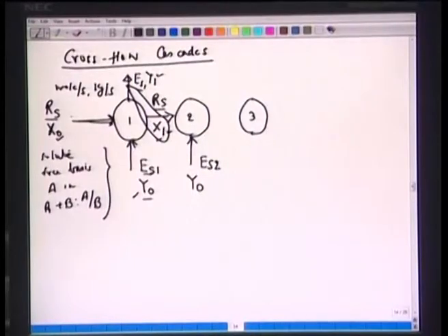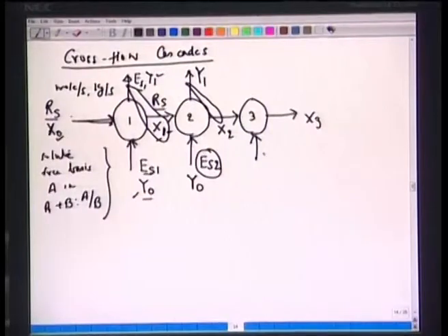To have more separation, higher than x1 or higher than y1, we have to bring it to the second stage, where again we bring this in contact with the fluid E with the flow rate Es2 with the mole fraction y0. They spend some time here. Again we can assume that if you have given enough time, the leaving streams with the mole fractions y1 and x2 would be in equilibrium. All right. So, similarly we have x3, we have y0 and we have y3 here. Excuse me, this should be y2.